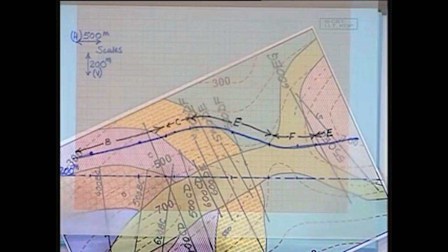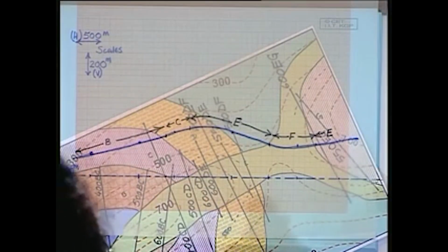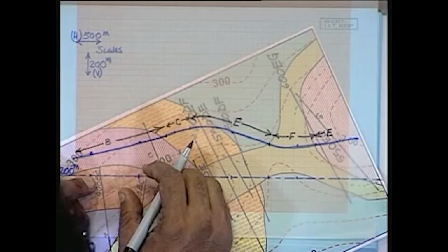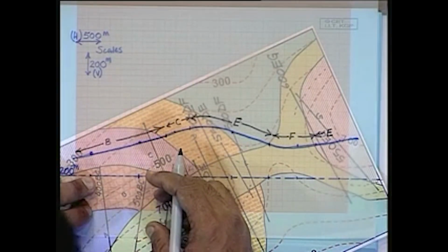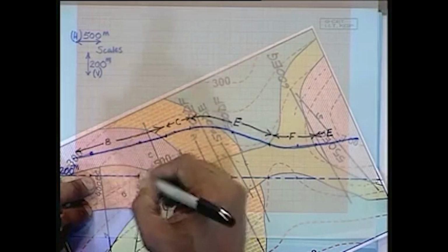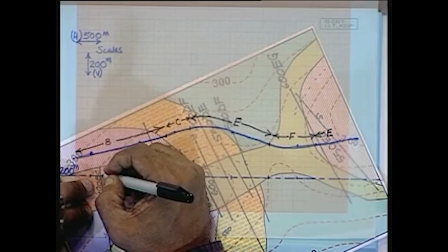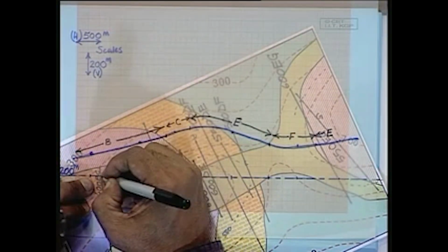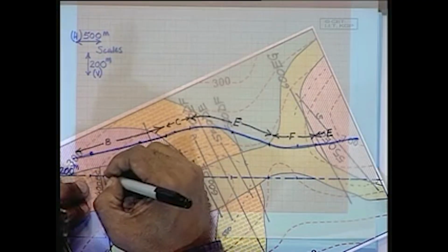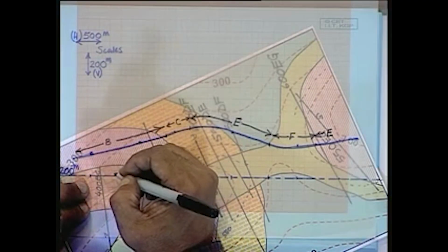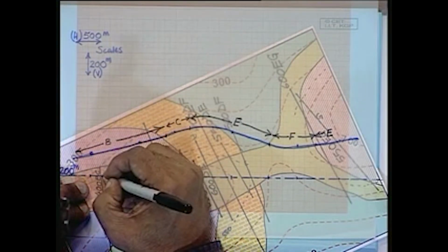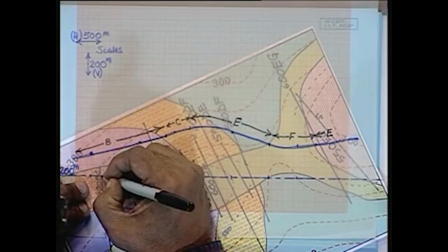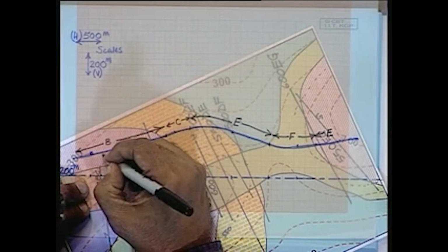Okay, so those are the outcrops that are going to be visible at the surface. Now let's start projecting upward the intersection between the strike lines and the section line. So what we are going to get, the first one is 400 BC. That is the intersection between units B and C, and it is at an elevation of 400. So that is at this location here.